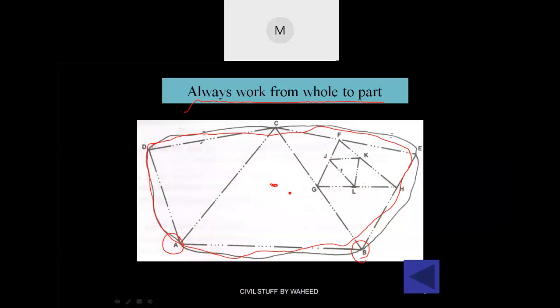First of all, if you have seen an area, you fix the points at the boundaries in such a way that from A, B should be visible, and every station should be visible from another station, the preceding station and succeeding station should be visible from every station. Like that you have to fix.